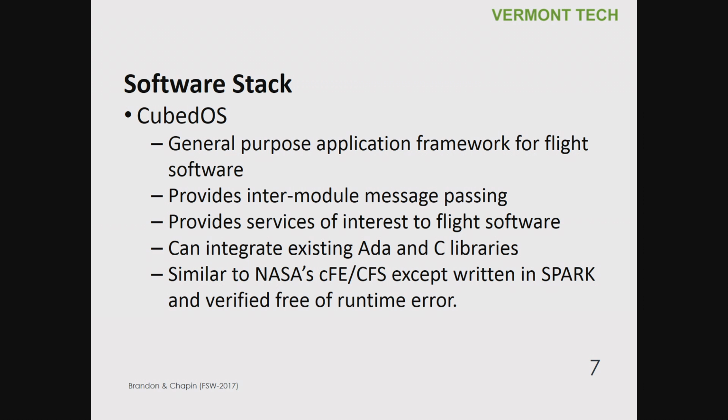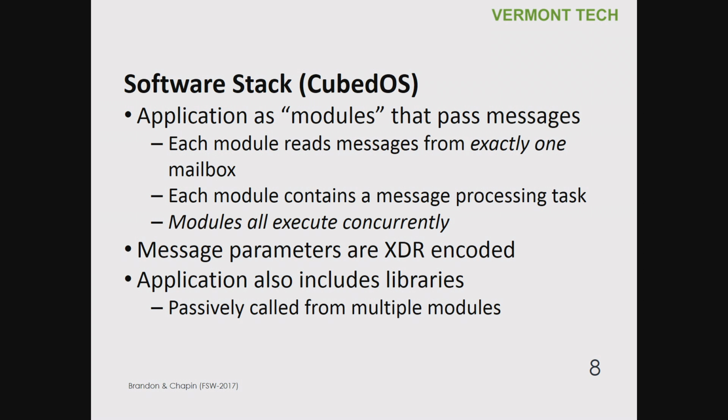The idea is to provide services of interest to flight software. This is very similar to what CFS is doing. We basically are writing all of our stuff in Spark or Ada, but there's no reason why you couldn't interact with existing C libraries, since that is a doable thing. And the last point I mentioned before about how we're trying to use the Spark tools to verify it free of runtime errors. I'll get to that in a minute.